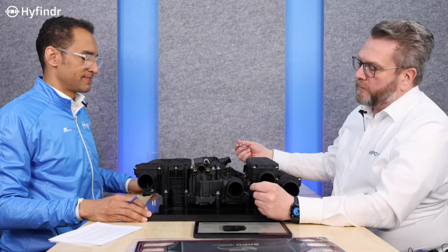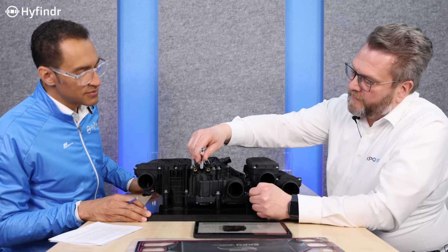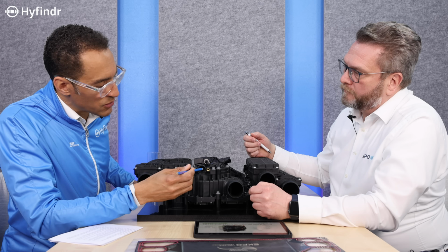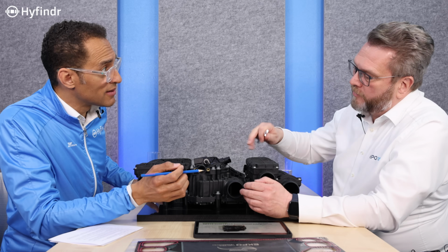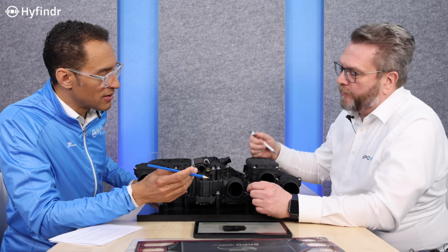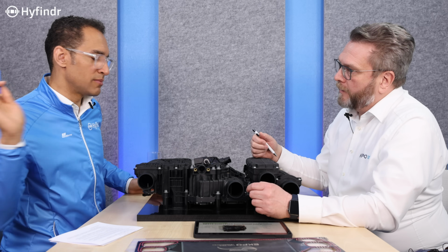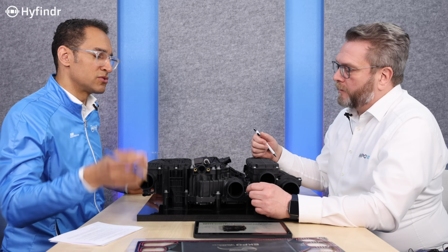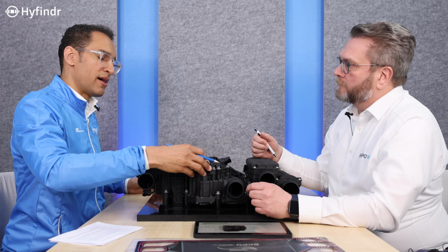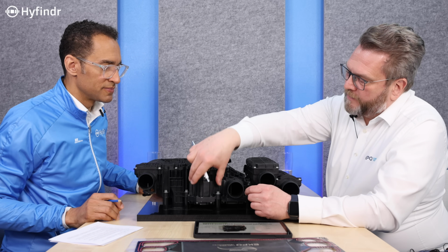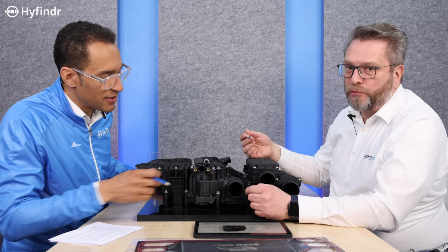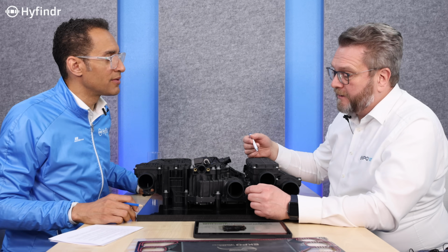So, as already mentioned, coming back to the hydrogen part, there's the inlet of the hydrogen. So what would you connect here? The tank? It's the tank with some lowered pressure. So we allow for 16 to 20 bars inlet pressure. Okay, so all I'm doing from the tank is getting a pressure reducer, 16 to 20 bar, and coming in here. Exactly. Just deliver it. Hydrogen is moving downwards. Here a heat exchanger is included, which is preheating the hydrogen in cold winter times, for example.